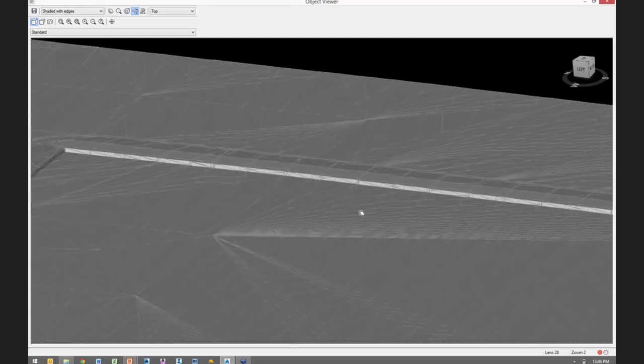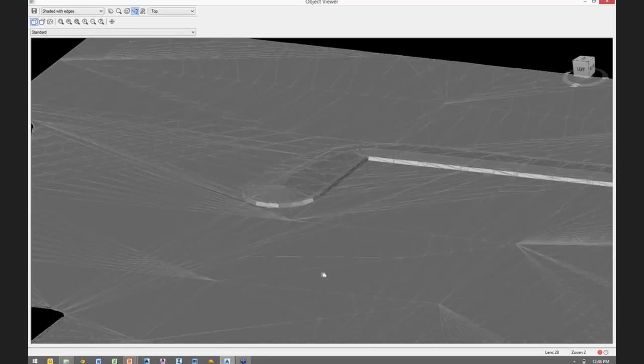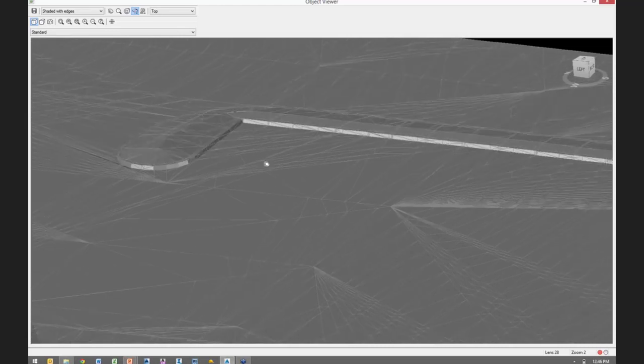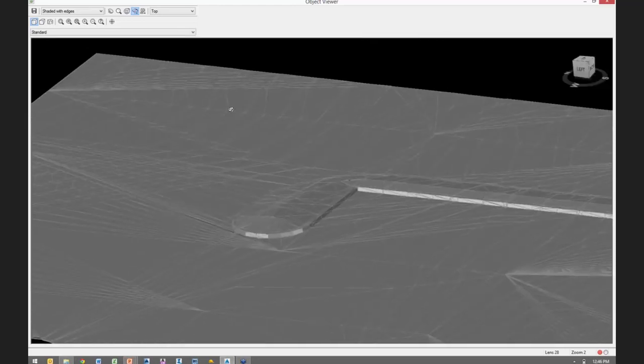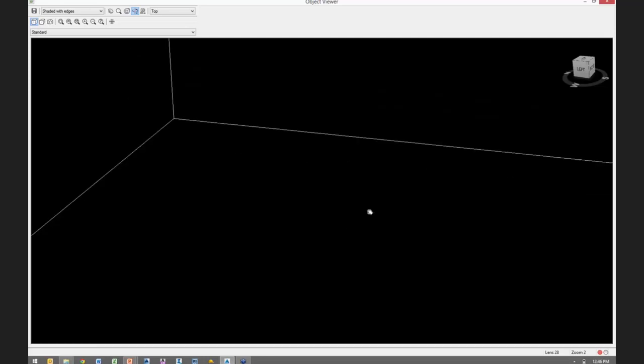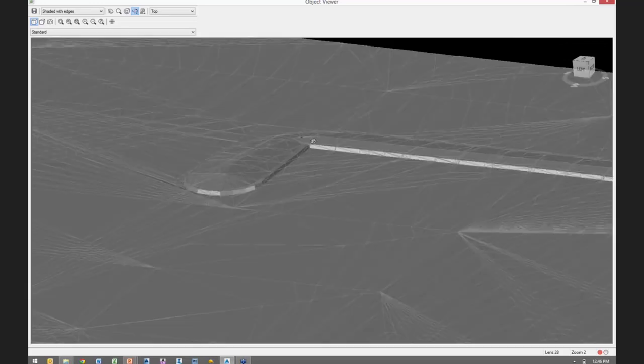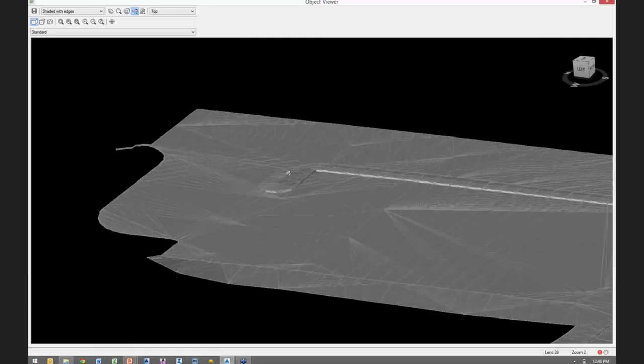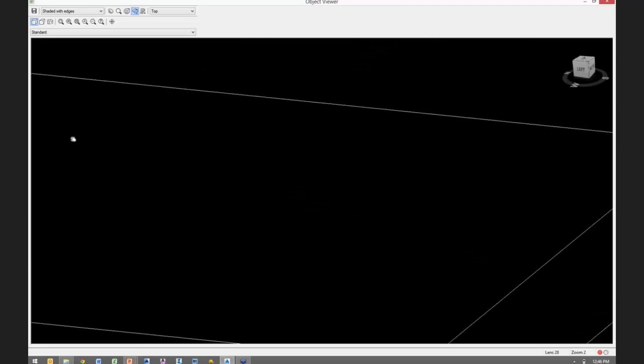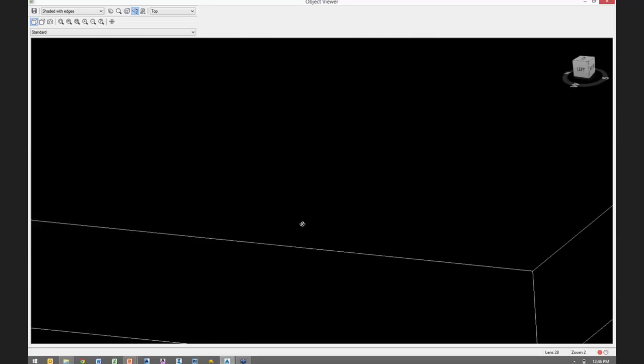This is my subgrade surface right here. This represents what I'm cutting down to or filling up to before I put my import materials down. So in areas where the curb islands are, I don't need to cut down as far. Let's look over here. We'll see the difference.